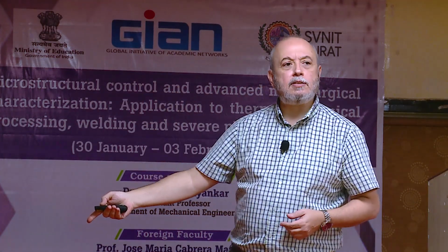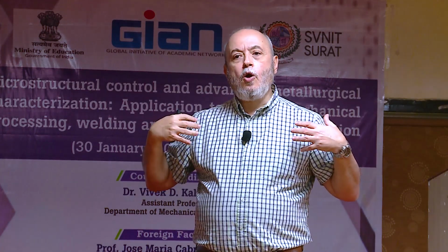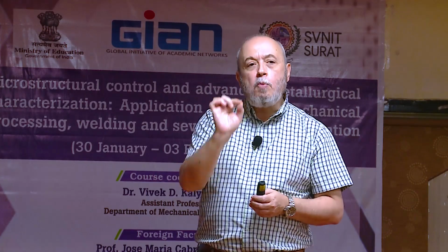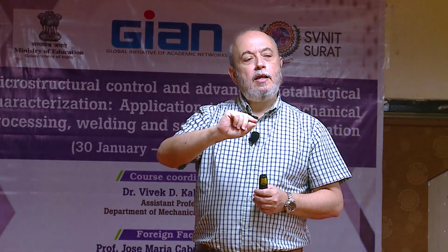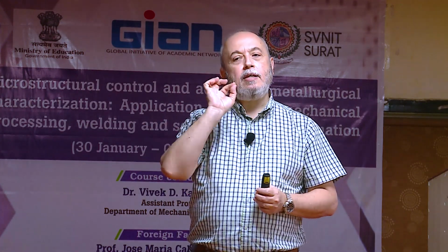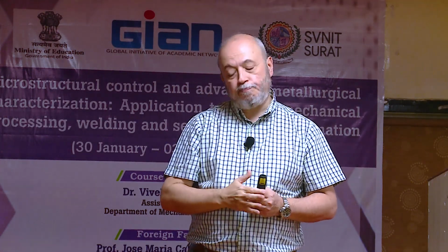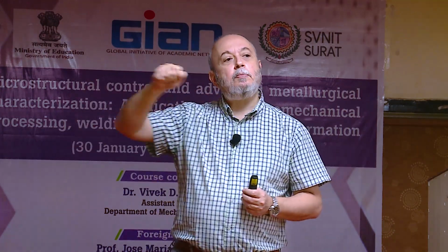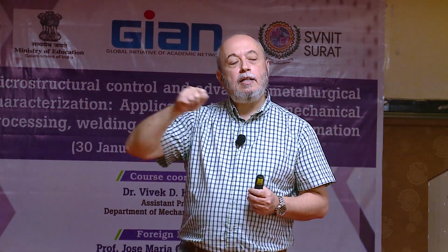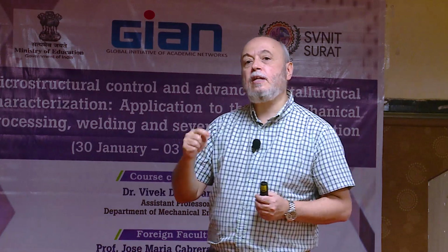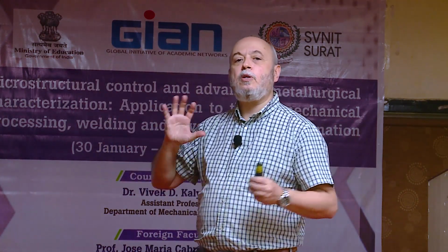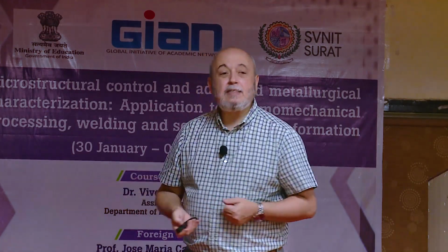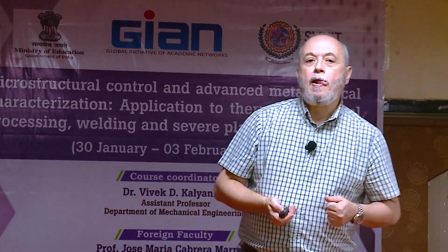Incremental forming processes. Instead of deforming all the piece in one single stroke, we can do small increments in the piece by just a sort of punch, and then distribute this deformation along the piece in an incremental way. And we will observe that we can deform much more than if we want to deform the entire piece in one single hit.